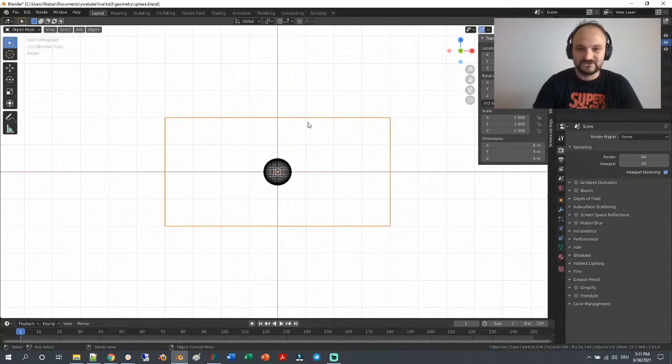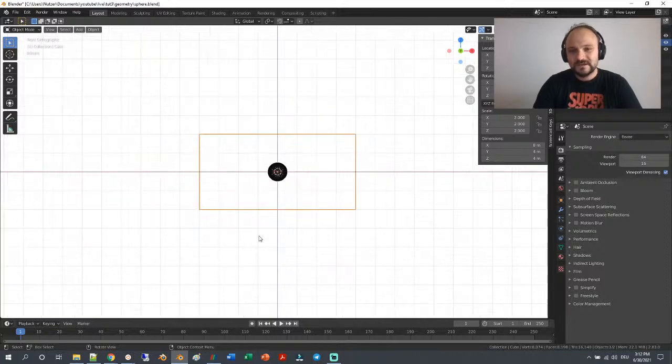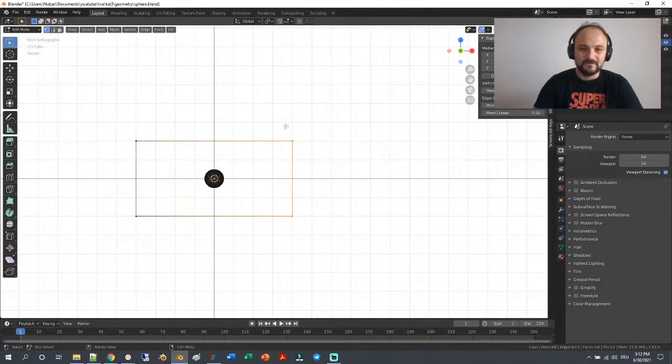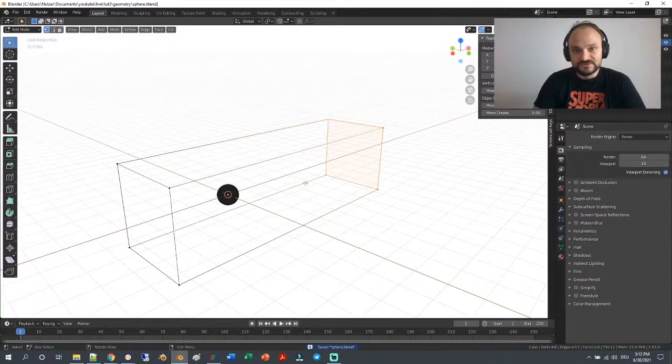So if the flow is coming from the left hand side and going to the right hand side, then this flow is okay in my opinion, but possibly we should extend the domain a bit further downstream. Maybe even 5. Okay, let's go for 5. Okay, and now I'm just saving this, and then let's just use these settings.